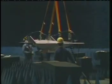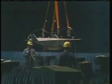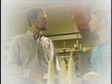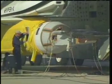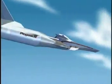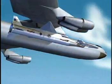How do they flight test the HyperX at such high speeds? Great question. The HyperX is a very small vehicle, about the size of 2 kayaks side by side. As Scott told you earlier, it will fly at about Mach 10. Now, because of its size, we only have enough fuel for use at the test conditions, or when the HyperX reaches Mach 10. How do you get HyperX to reach Mach 10? The HyperX is attached to the nose of a rocket. The rocket is mounted under the wing of a B-52 jet. Let me explain what happens.